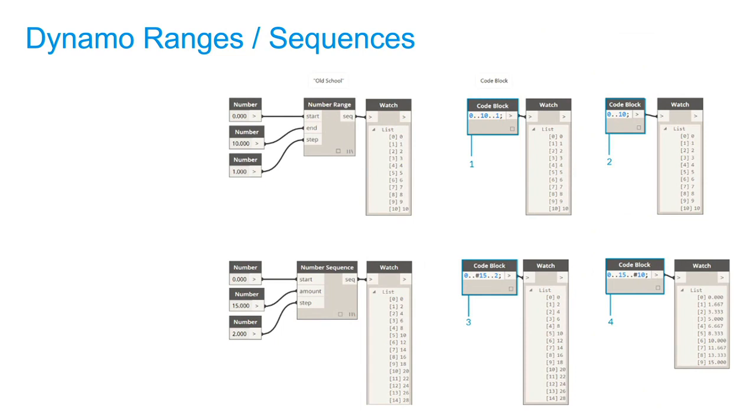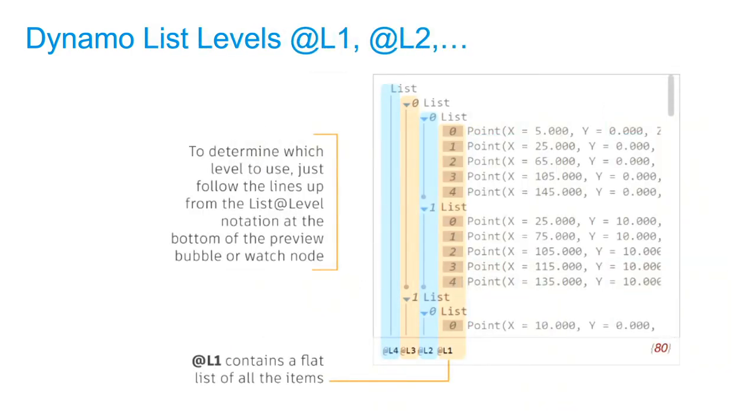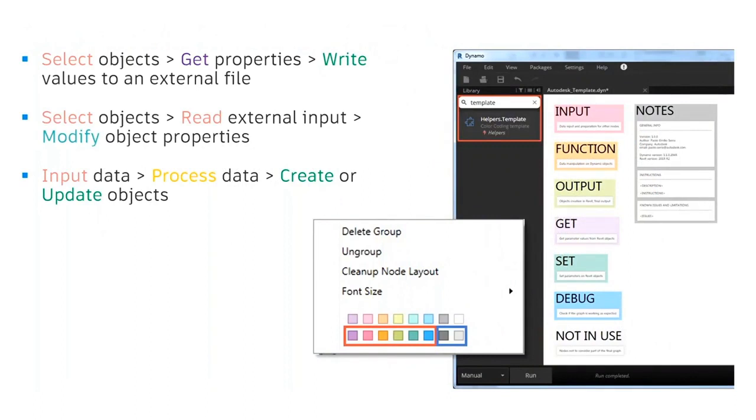It's very important with Civil 3D to understand two things in Dynamo. This is, I think, a little bit different than Revit: ranges, sequences, and lists. Civil 3D saves the feature lines and the other lines, alignments. We have points, and these are usually saved in lists like a database. Tapping into the lists in a certain way, changing the order of the lists or extracting certain information is very important. But there are many nodes dedicated for that inside Dynamo.